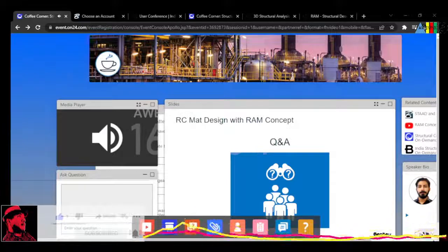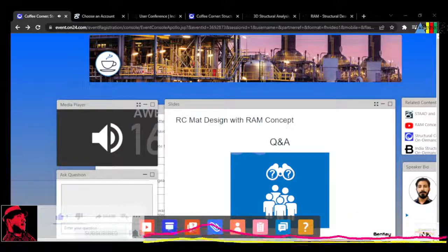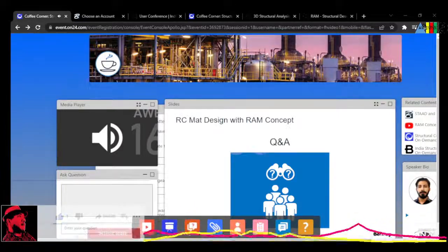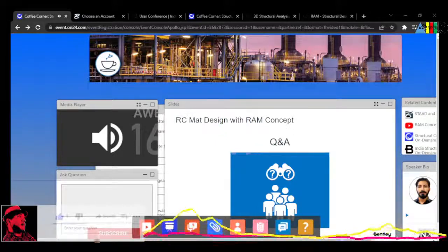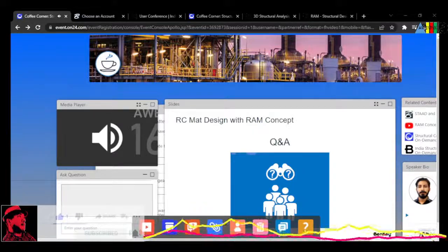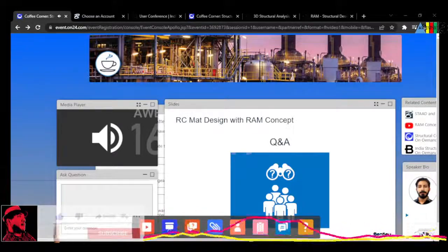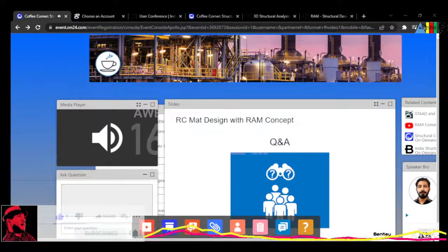Those sort of diagrams are not generated for walls, and because of that, the deflection plot and stress plot in the slab are around the same range, so the plot is very easy to read. But if you use the beam, then you will get some issues, although not very critical to comprehend the results. I'll get back to you again on further details by referring to the product manager and the manuals.